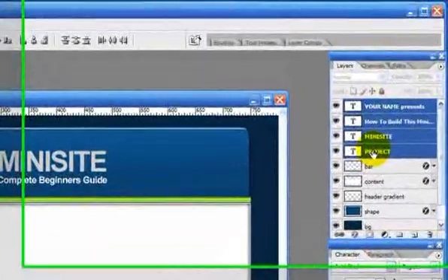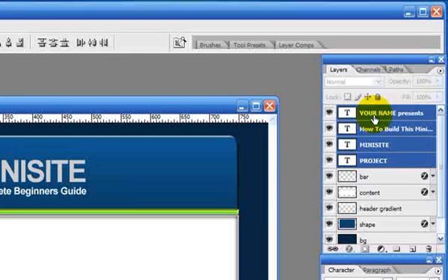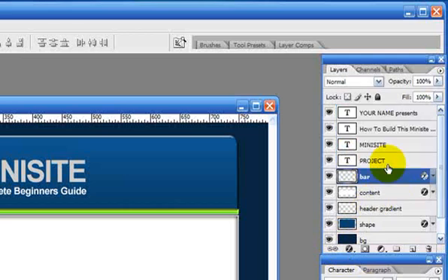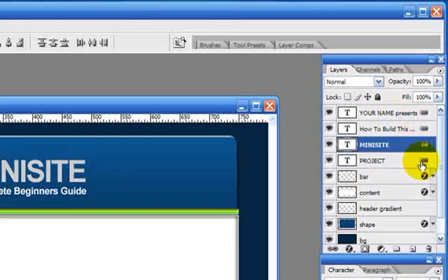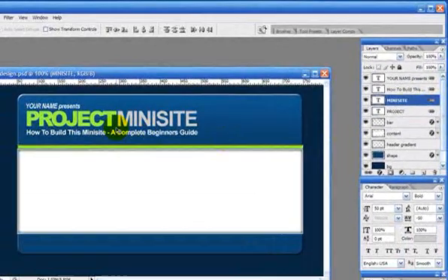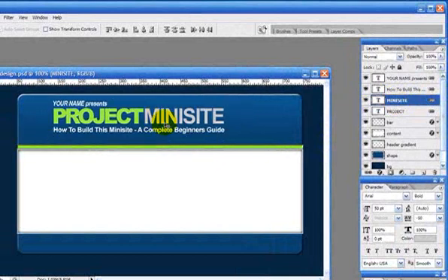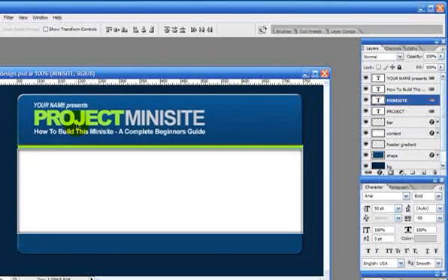And I'll just show one other thing in this palette menu. Once you have all these 4 selected, there's a little icon down here, and as you can see it says link layers. Now if we click that, you can see it's brought up a little chain link on each of these layers. If I select another one, you see the links disappear, but if I select just one of them now, you can see that the 4 links are on there, and with only one selected, if I try to move it, it will move all 4, because they are now linked, which is again very, very useful.